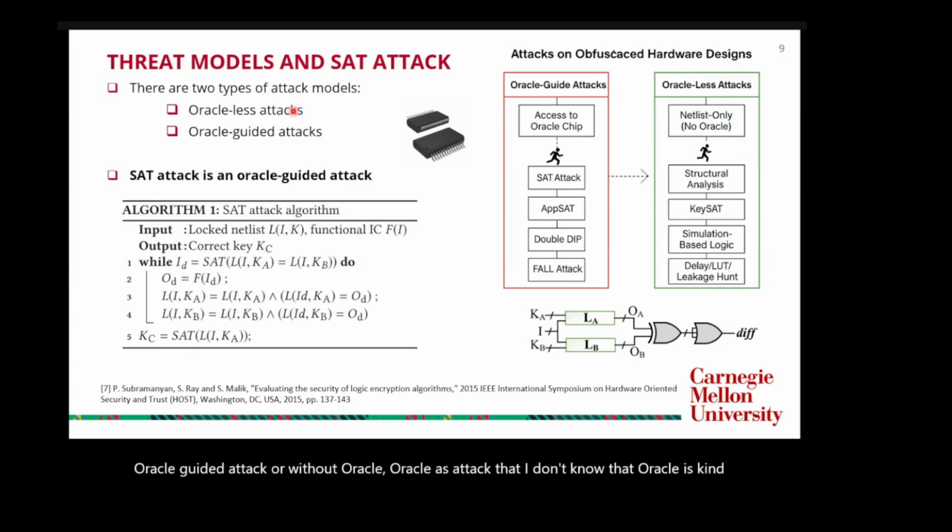After strong logic locking, there was a very successful attack in 2015, and this attack is the SAT-guided attack, and it is very famous. We call it the SAT attack, right? The SAT attack actually broke every 3 or 4 types of the logic locking techniques in seconds. It just ran and tried to break the key in seconds.